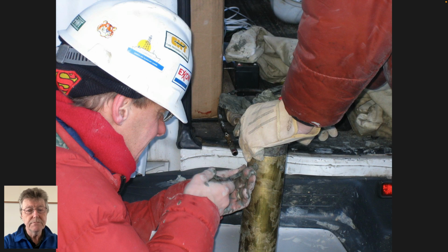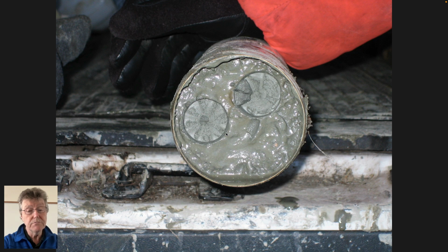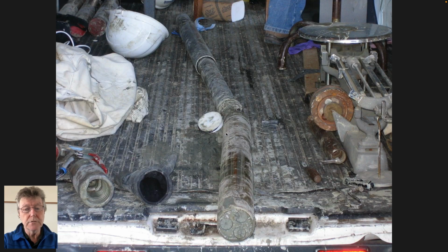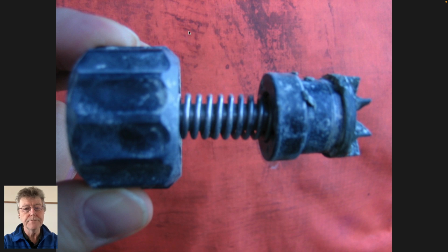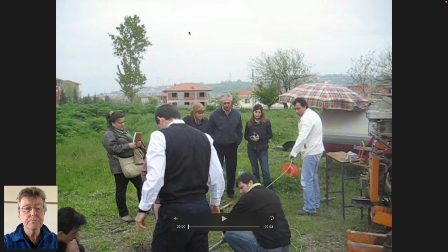The end of it. Taking out, removing those screws. Torque vane for measuring the strength. You might not want to know the strength, but there are other applications in foundation engineering where that would be a typical thing to measure. Yeah, torque vane. So it just measures how much torque you apply before it finally gives, and it measures the remnant torque that it got up to, just like a dial on a watch strap. Yeah, all it is. Okay.